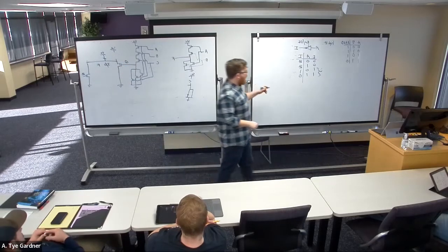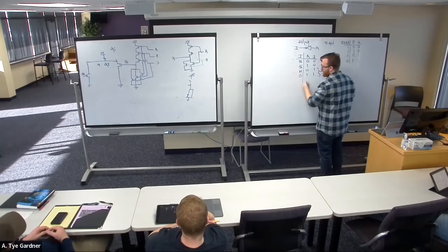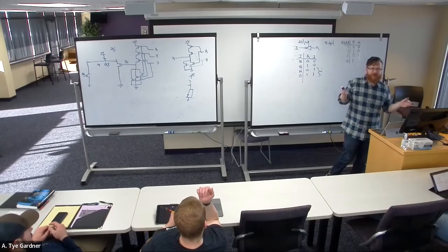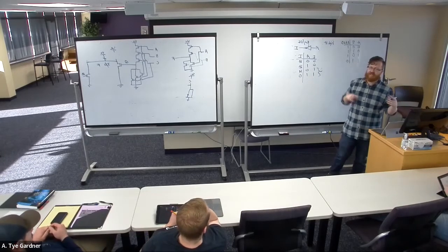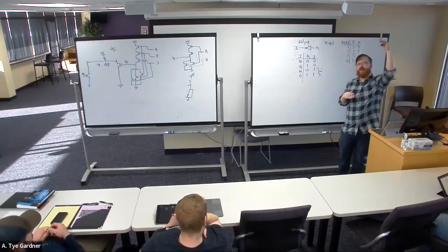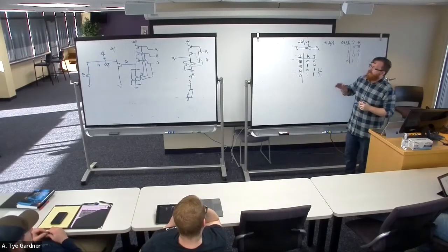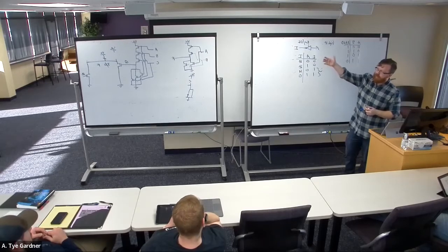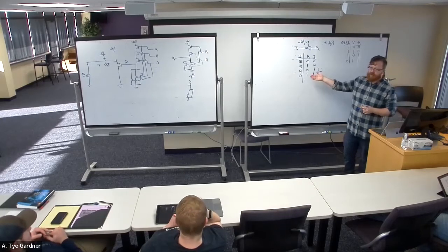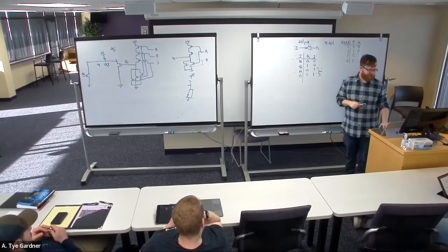So instead of writing 1, I write high. High is basically 1, right? The incoming digital, the receiving system is going to recognize high is a 1, but it's different because it's not quite all the way to VCC. If we inverted that, right, we could use a PMOS the same way in a pull down resistor. Then we would have, instead of 0, we'd have low because it wouldn't quite reach ground ever.